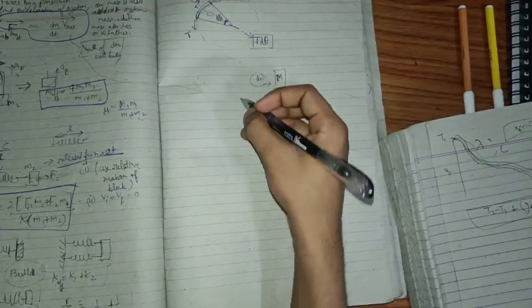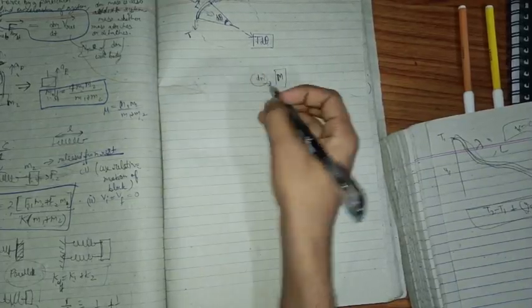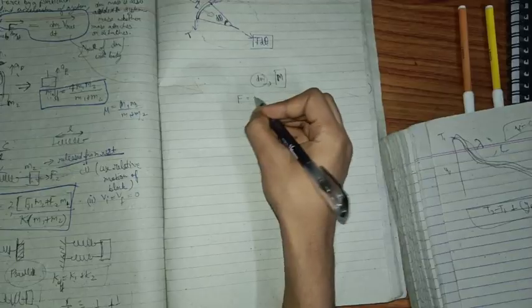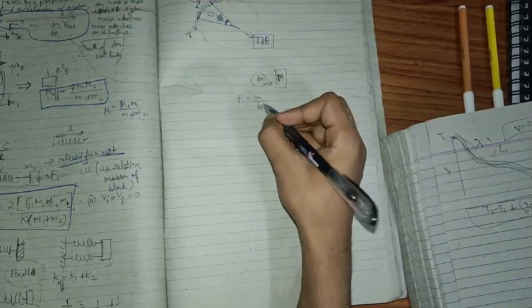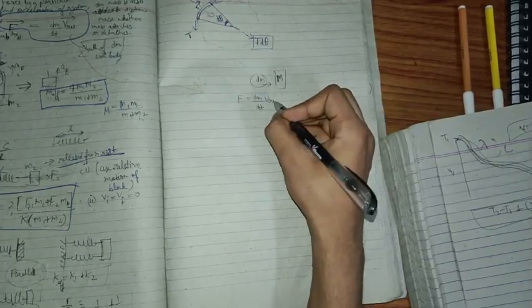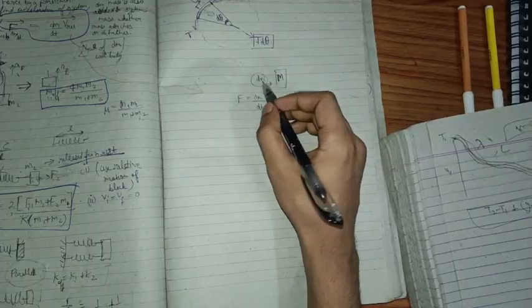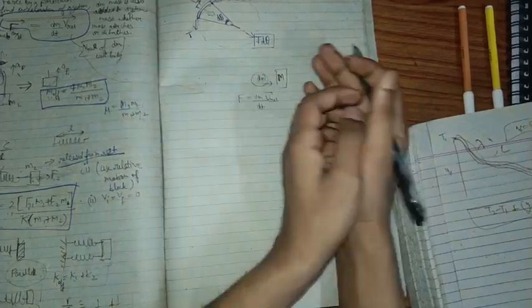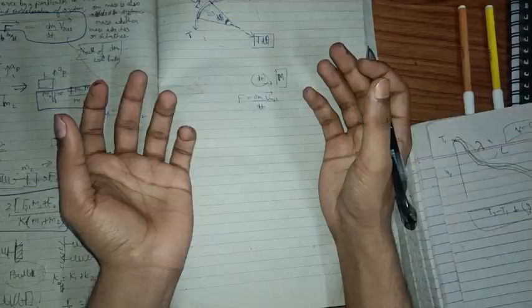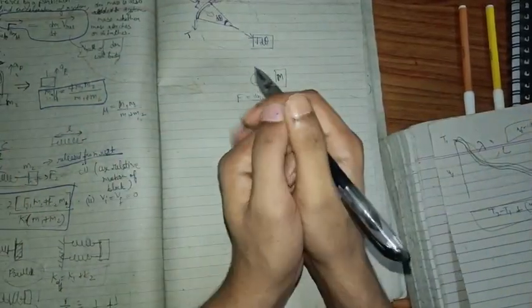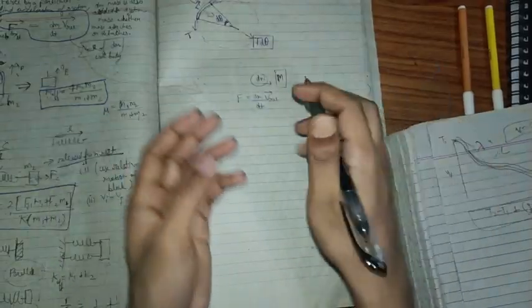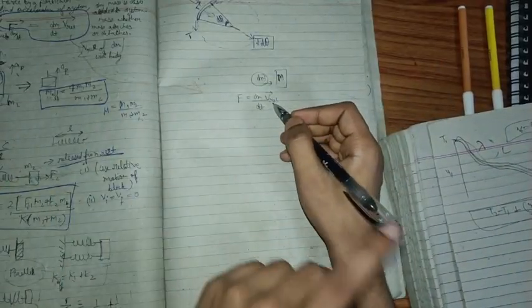In that case the force applied by this dm mass is given by dm divided by the time taken, times the relative velocity. If it is going to attach to the mass, we take the initial relative velocity, and if the mass is getting removed from the system, we take the final relative velocity,